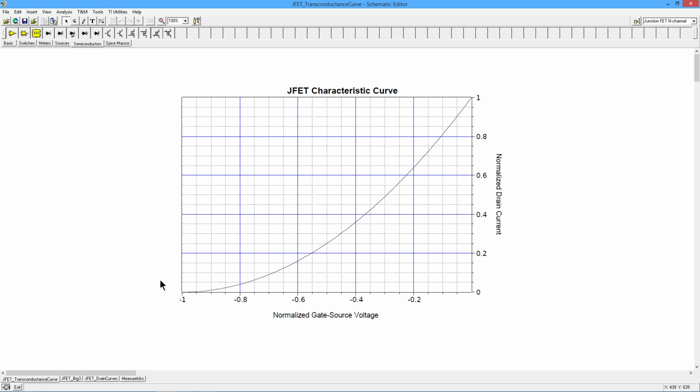and at the opposite extreme we have VGS off. So if I need that for all my analyses, how do I go about getting those values? Well, you can look them up on a data sheet, but when you do, you immediately see a problem, and that is you'll typically be given a range of values. So they might say, oh, IDSS varies from 4 milliamps to 20 milliamps. Well, that's a pretty big spread. And they might say VGS off varies from -2 volts to -8 volts. Same deal, big spread. What do I do?